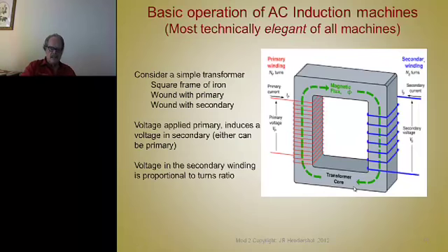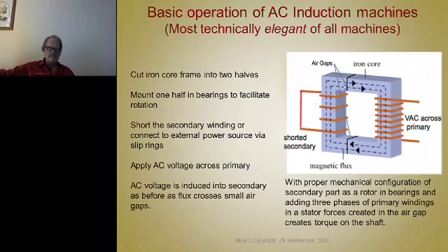Let's take that same transformer. Let's take a big hacksaw. Let's cut it in half. I didn't get these two cuts lined up, but they're supposed to be lined up. So we cut this in half, and we've got a little air gap there. And now I've got the primary on this side, secondary on this side, and I short this secondary. This shows 4 turns there, but in a shorted secondary there's really only 1 turn. But consider these different bars all in parallel.